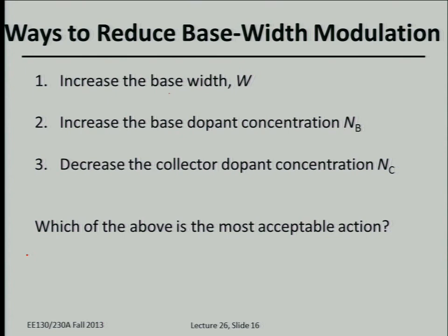More recombination, that's right. More chance for carriers to recombine before they get collected by the collector. So in terms of transistor performance parameters, what does that mean? Less gain, that's right. Gain is a function of the emitter injection efficiency and the base transport factor.